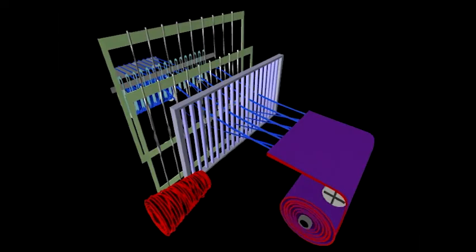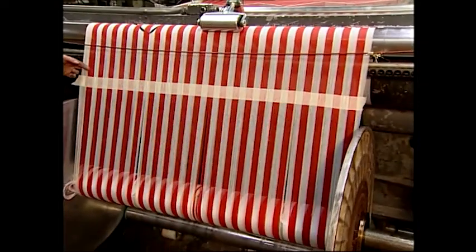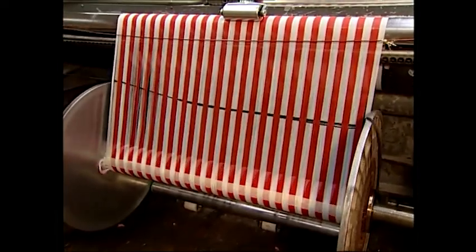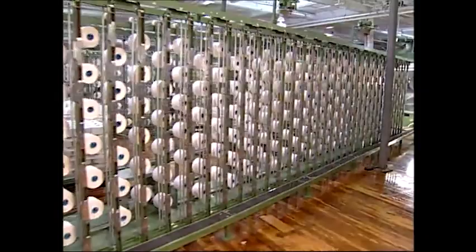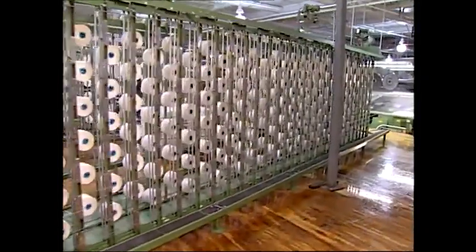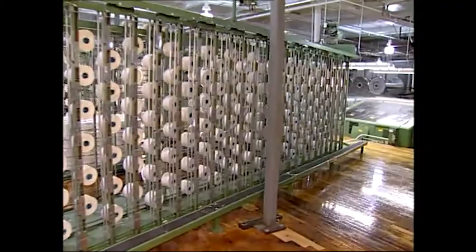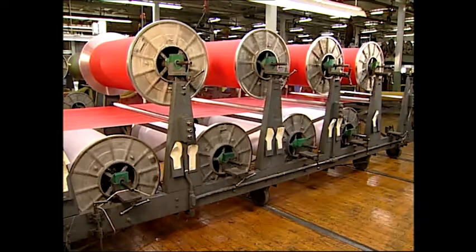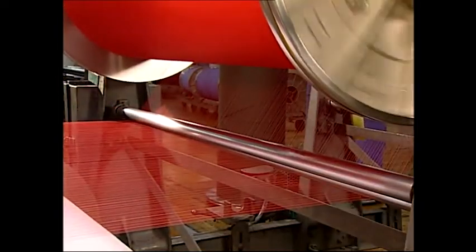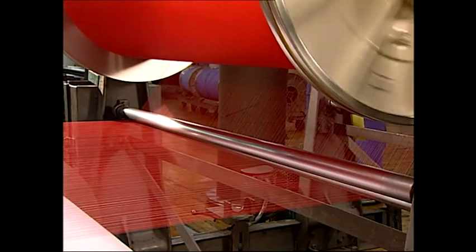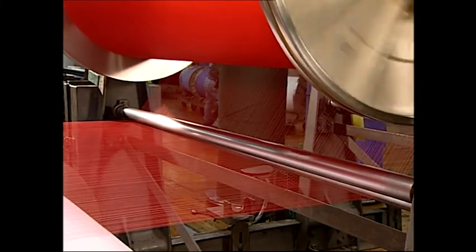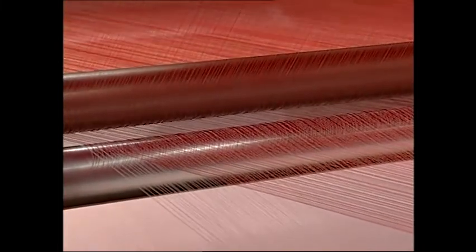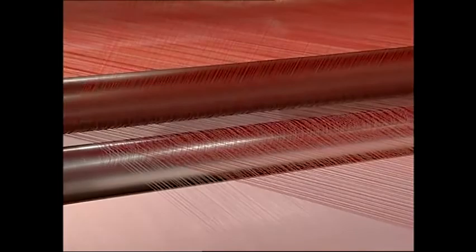This section will guide you through the basics of weaving. A loom beam contains thousands of individual yarns placed side by side onto a flanged beam. In order to have the necessary number of yarns on the loom beam, one must start with yarn packages in a creel. It is not possible to put all the yarns needed for weaving into a single warper creel. For example, if the warp beam needs 3,200 ends and the creel holds only 400 ends, then a section beam will be made on the warper. Therefore, 8 section beams would have to be made to accumulate the needed 3,200 ends.